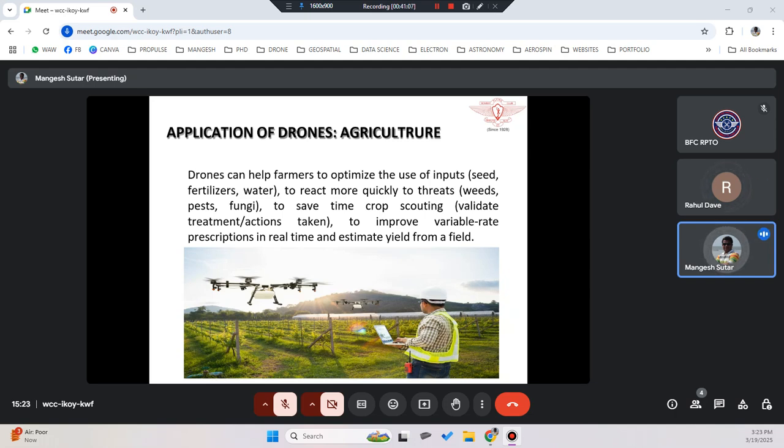So basically, in the traditional way, when you are putting fertilizer or pesticide, let's say you are utilizing 200 liters of water and maybe 5-10 liters of fertilizers. But if you are deploying a drone to do it, we have seen that people only require, for an acre, I'm talking about an acre, hardly 20 liters of water and just 2 liters of pesticides. See how, from 5 liters of pesticide you are reducing it to 2 liters. 200 liters of water is reduced to almost 10% of it, so only 20 liters of water is required. Okay, so much saving is there.